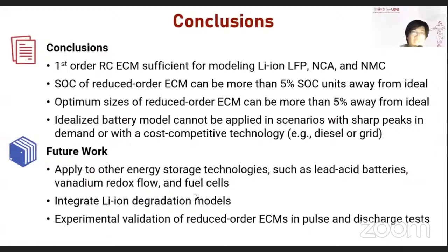So to conclude, we found that the first order RC model is sufficient for modeling the lithium ion LFP, NCA, and NMC chemistries. The SOCs and optimum sizes between the reduced order ECM and the idealized battery model can differ by up to 5%.